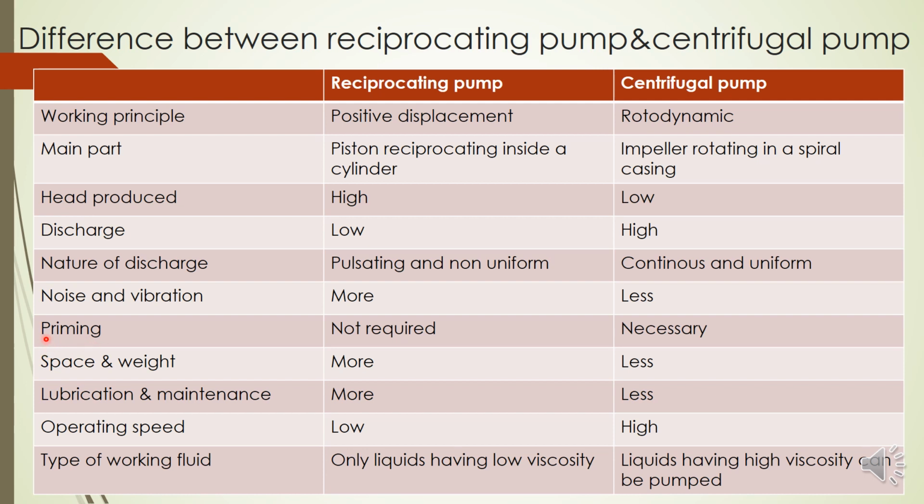Then another important point, priming. It is not required in reciprocating pump. Even if only air is there initially in the cylinder, it will work. But in centrifugal pump, it is a must. Priming is necessary. We have to fill water in the casing and suction pipe.